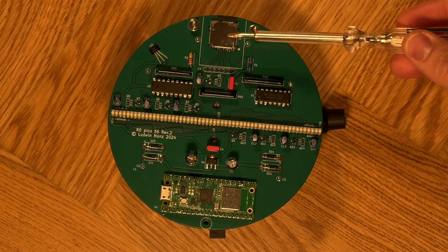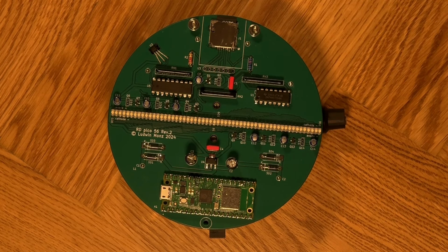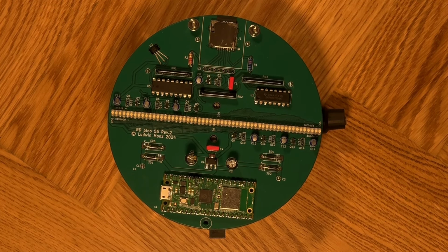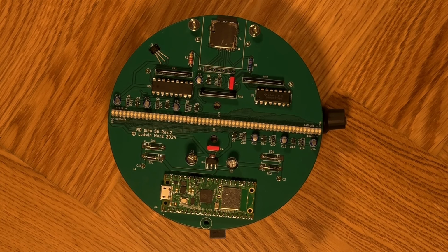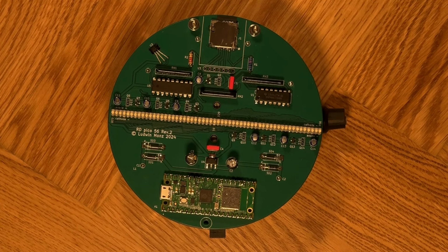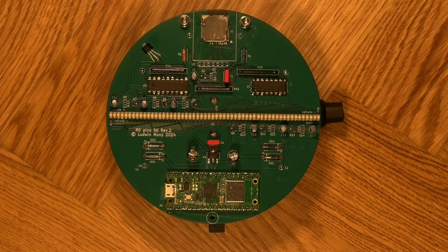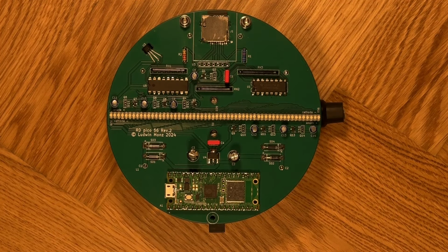The SD card reader is located at the top of the display. The SMD component can alternatively be replaced by an easily solderable SD card adapter. The last component that I would like to mention is the Hall sensor on the left side of the display. It is needed to create a spatial reference point. This is the structure of the display board.